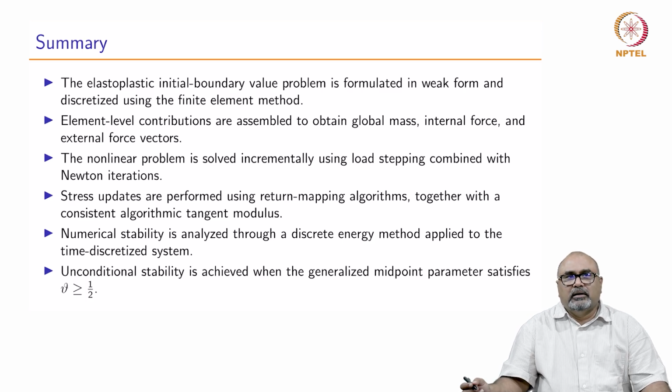The nonlinear equilibrium equations are solved by using an incremental iterative algorithm following a Newton iteration, and we have understood how to linearize to get the tangent stiffness or the tangent modulus, and the stress updates are performed using the return mapping algorithm together with a consistent algorithmic tangent modulus.